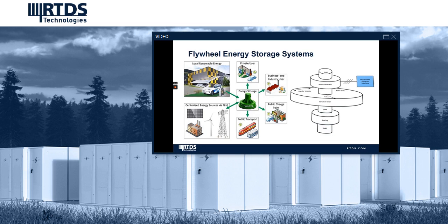In charging operation, which occurs during periods of excess renewables or excess power generation, the flywheel power converter control accelerates the flywheel motor and draws electricity from the grid. In discharging operation, which occurs during periods of low power generation, the flywheel decelerates the motor to supply electrical energy to the grid. The state of energy of a flywheel defines the amount of kinetic energy that is stored or delivered during its charge or discharge period.